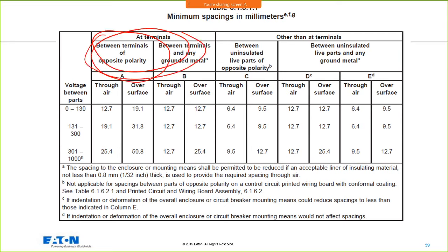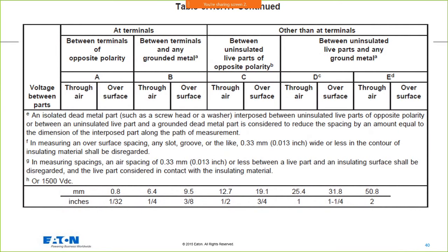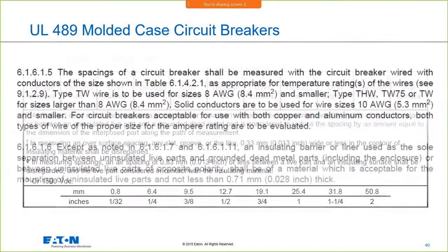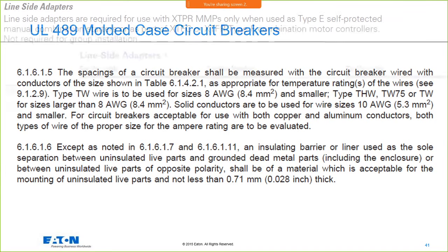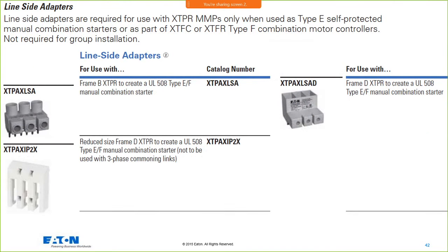If you look at the terminals, they'll tell you from a manufacturer's perspective, I'm maintaining certain distances, and I'm doing certain things in testing to make sure I don't have tracking over these conductors and across terminals, right? And you may see barriers built in. You may see some fins and go, why did they put this big piece of plastic here? It's because I need to pass some of these tests when we test the UL 489 device. So you can't just say, I'm going to break this off because it's in the way, right? That would be ungood.